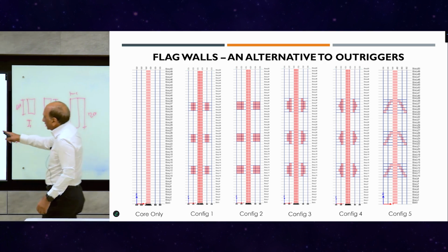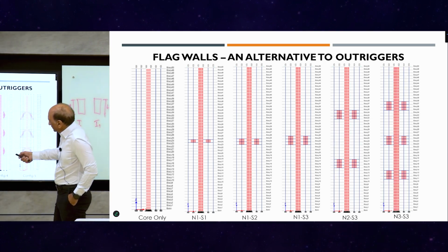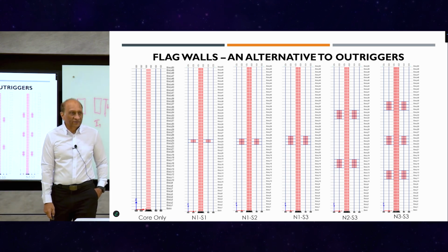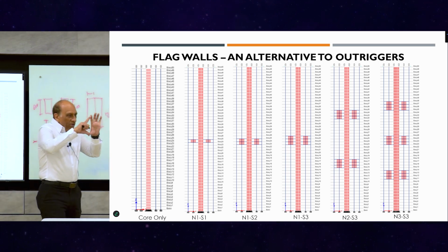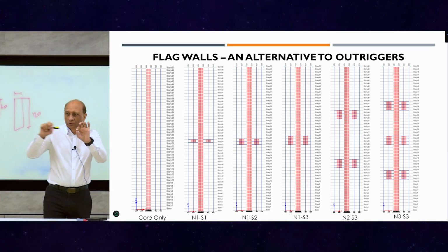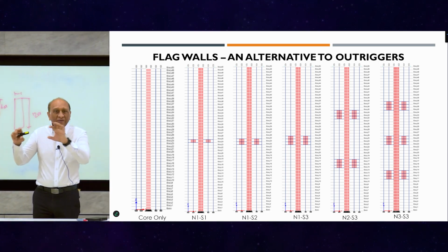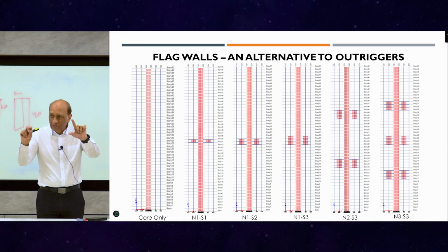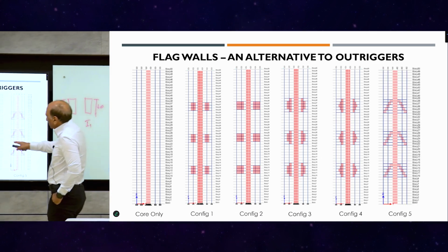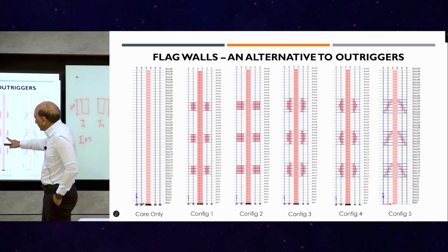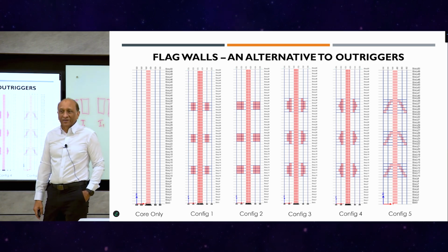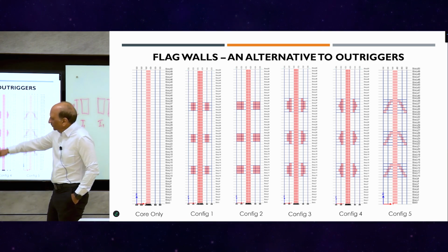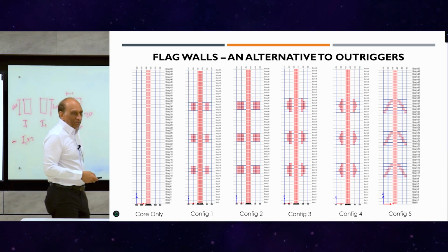So that's why we studied all these options, because we had a problem in this area with the local effects of the beams connecting there, because suddenly there is a huge transfer of forces from the wall to the beams close to that, and those beams fail because the stiffness changes so rapidly, right? From very large stiffness to just no stiffness. So that's why this is a way to solve that problem, gradually reduce the stiffness, or gradually increase the stiffness. And then another way to do that. So many possibilities are there in flat walls.